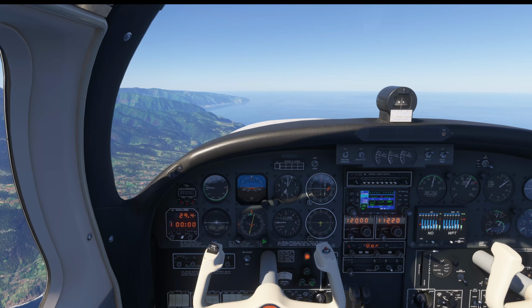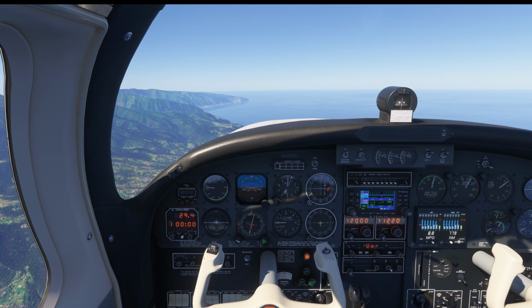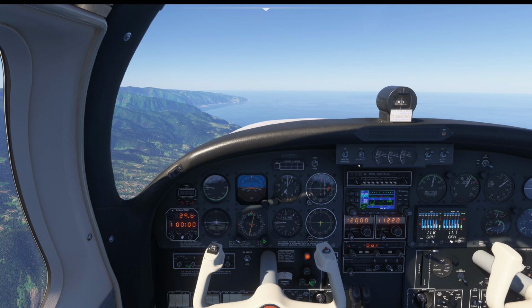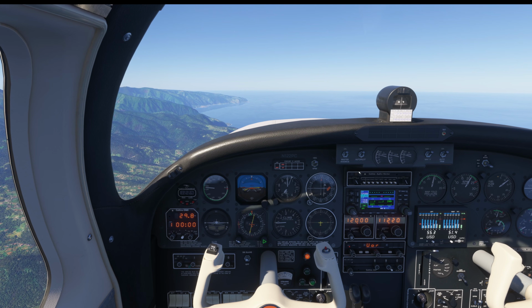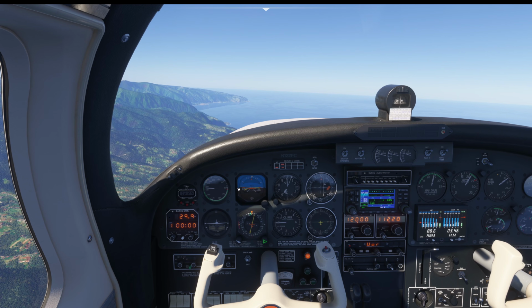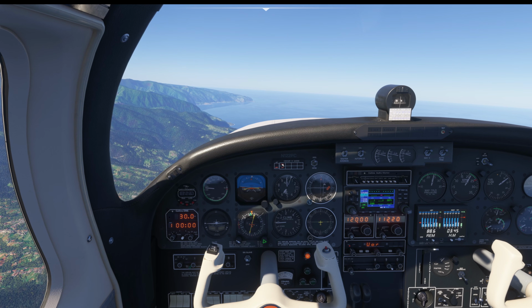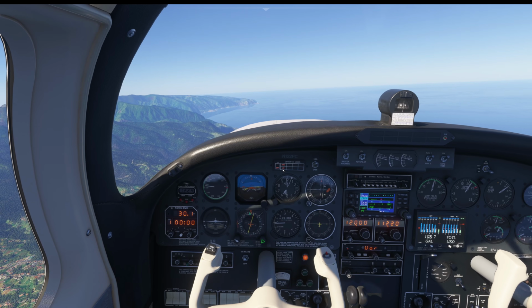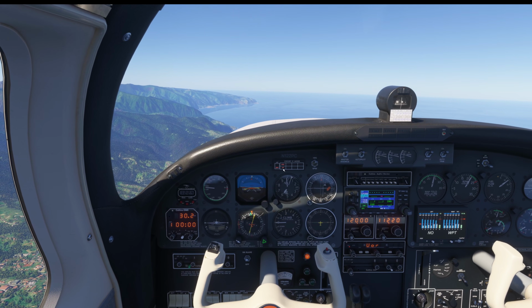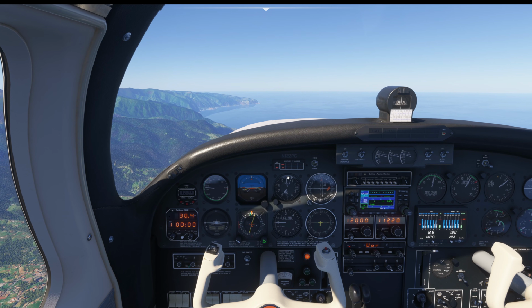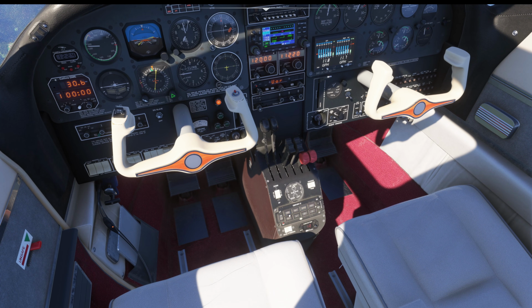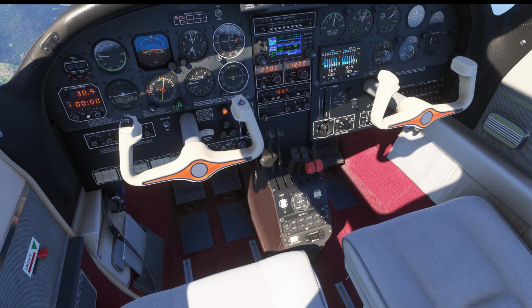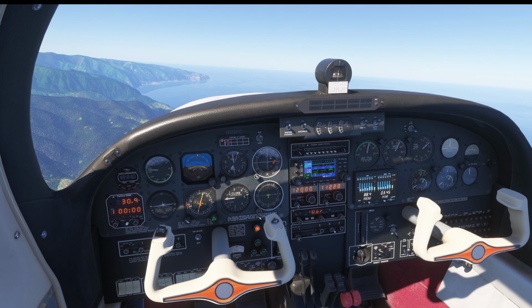Now we're flying, so let's look at how to engage the autopilot, because it's a two-step process. First, set the master switch to on. When you do that, the flight director comes up and the autopilot guidance starts in heading and attitude mode, but you are still in control of the aircraft. You can activate other modes if needed, and when you are ready to engage the autopilot, press the on-off button on the pedestal. The autopilot will take over and follow the computed guidance as shown on the flight director.